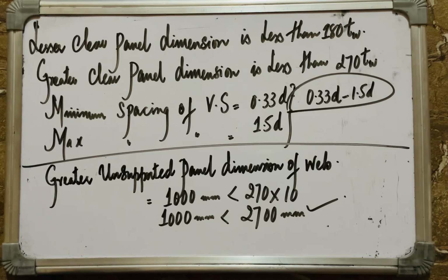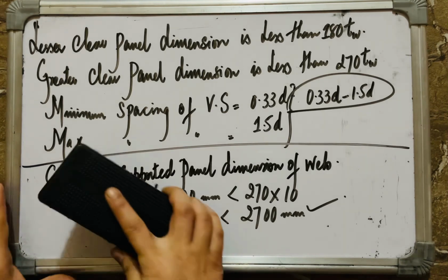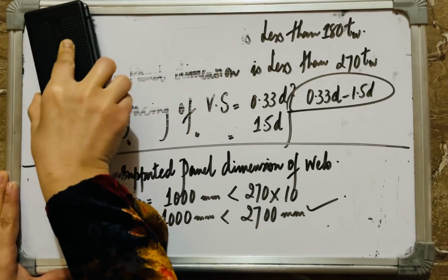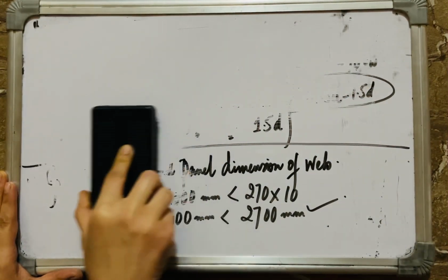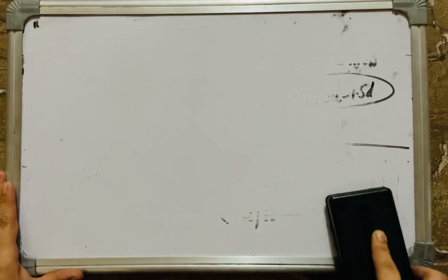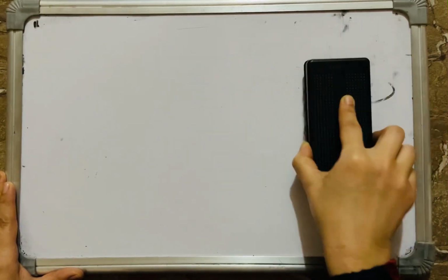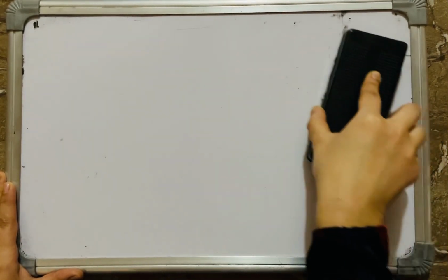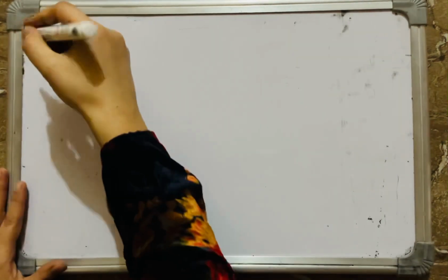All right. Now these intermediate stiffeners, which are vertical stiffeners in our case because as per the d/t ratio, which came equivalent to how much? 100. So it was just greater than 90. It fell in category number 1. So our intermediate stiffener in this case of a steel truss bridge is the vertical stiffener. Now these intermediate stiffeners can be vertical or horizontal stiffeners, but in our case they are vertical stiffeners. These intermediate stiffeners are designed to have a minimum moment of inertia, which is specified as, I'll write it down for you.